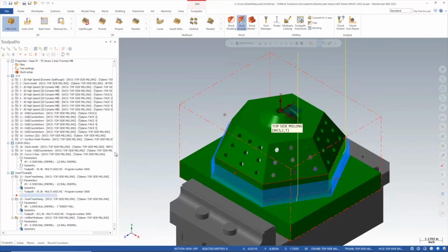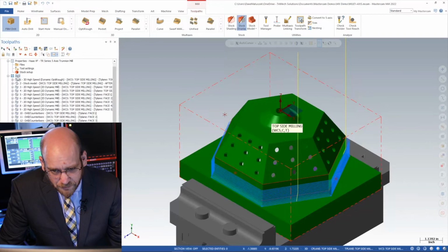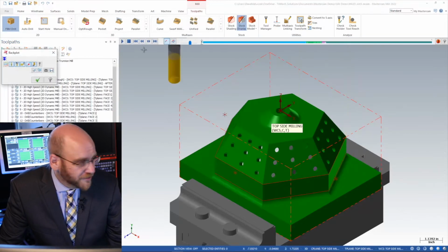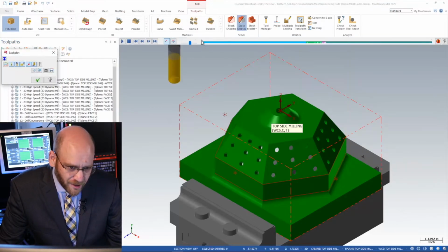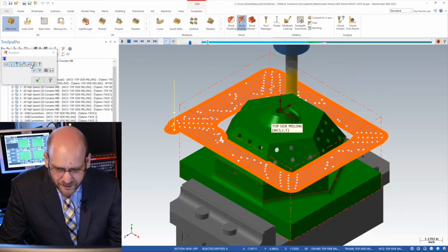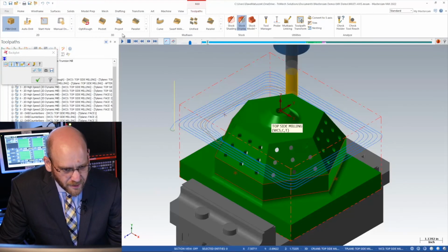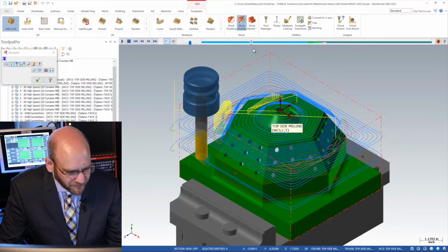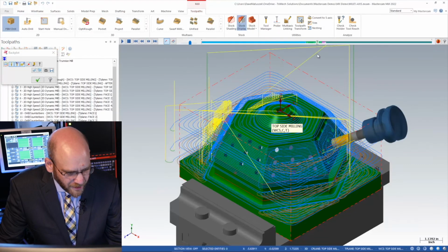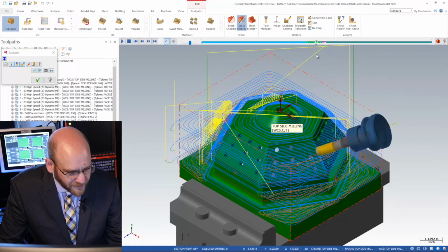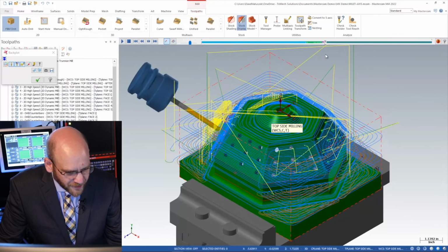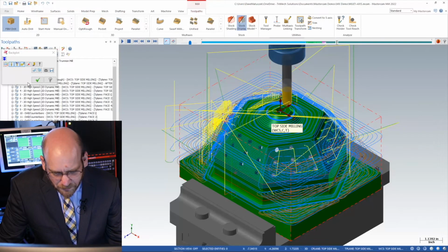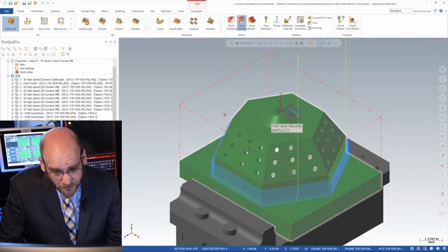Let's say we have a part similar to this. This part actually has a little bit of everything on it. But you have the ability to do basic 3+2 machining right from standard 2D toolpaths. All I'm doing here is machining this in one axis to rough it out. And I'm creating planes, just 2D planes, to do the other faces. So for example, let's say I want to machine this face. That's the only one I haven't done yet.